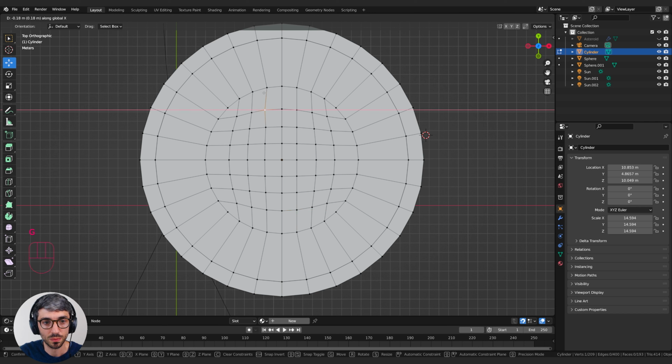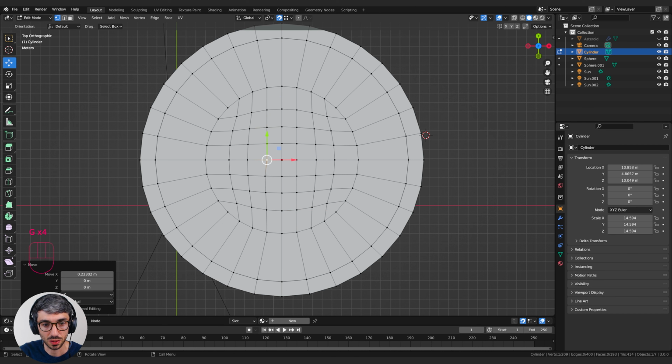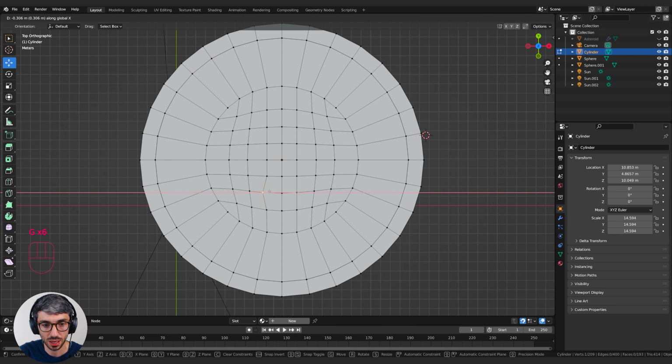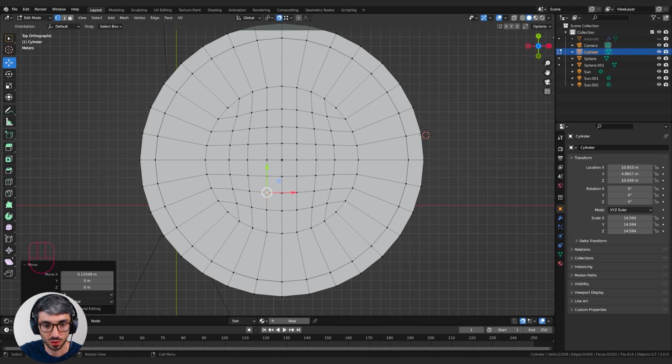And then I'll do this one as well, this side. Well, that makes sense. What I'm doing there is I move my mouse up. So click G to grab, X to lock it on the X, and then just move my mouse over the one that I want to borrow the X position from. There we go, great. So these guys are all nice and even now.